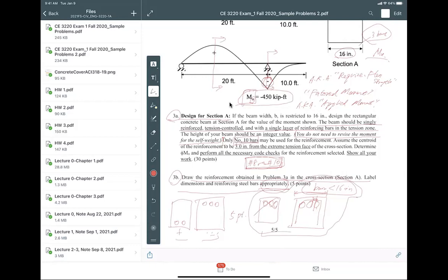That's what matters. All right, now if you have trouble getting the clear cover of the concrete, any clear cover thrown in here is fine. Okay, you can say 1.5, you can say 2-inch, but I require you to put a condition behind it. If it's 1.5, you need to tell me it's an interior exposure from the table, or exterior exposure for 2 inches from the table or not. Give me some reason so you can justify your clear cover dimension selection.